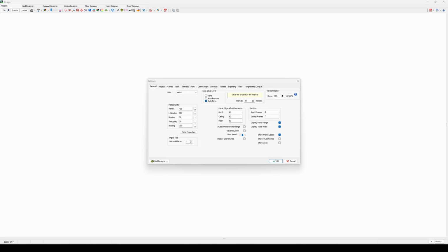is called bracing or lintels or lattices, whatever the case might be. Now, when you start achieving a very large opening, what you might want to do to strengthen those lintels or lattices, whatever you want to call them, is to add plating material. Plating material being sheet metal attached onto the sides of these lintels by using tech screws.